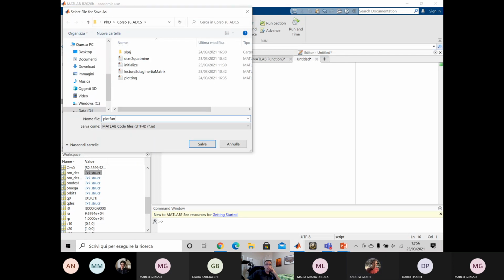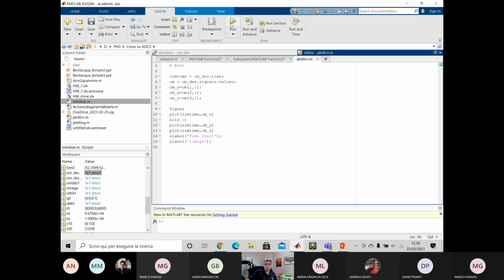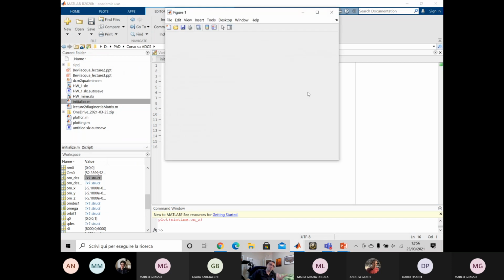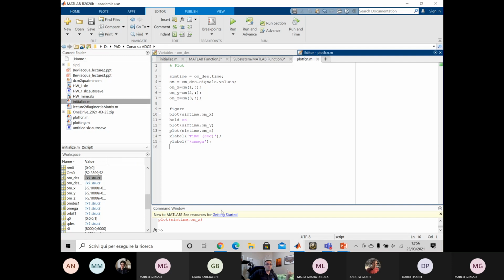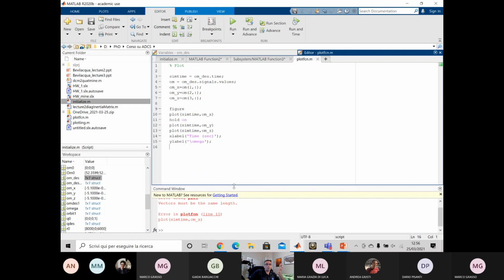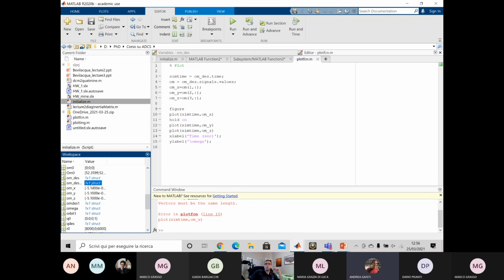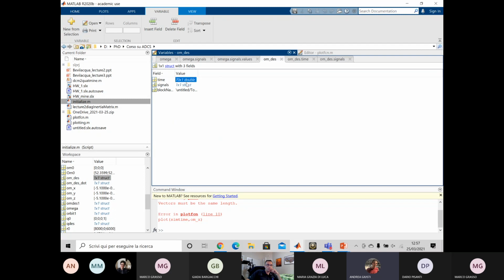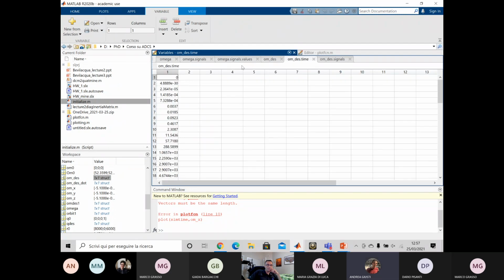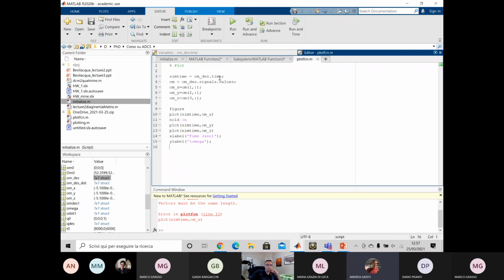The principle is the same: it takes in the torques, the commanded actuator positions and rates, and generates as output the angular acceleration of the spacecraft, exactly like it's happening now in the Euler's equations block, which is very simple. It will become a little more elaborate because in this case the actuators are embedded in the process, so it's not that easy to decouple the two systems. Yeah. Okay. The actuators are part of the dynamics. Okay, I see.